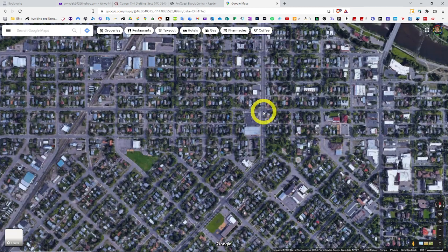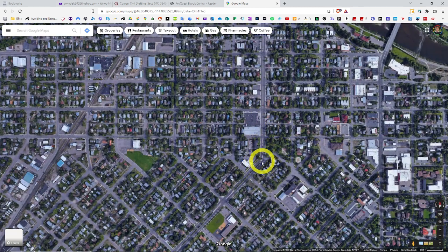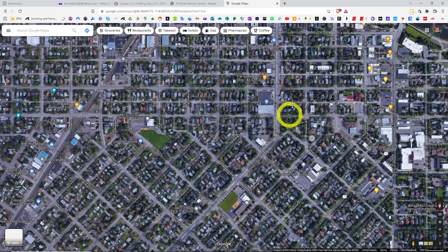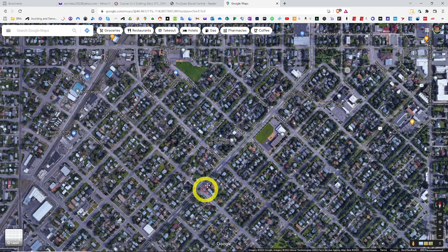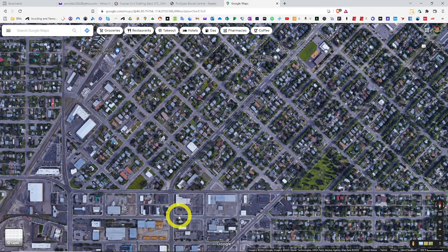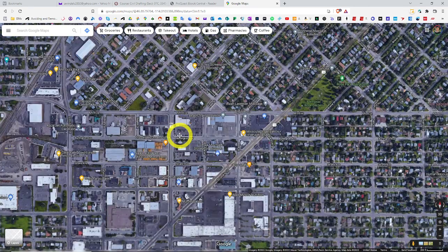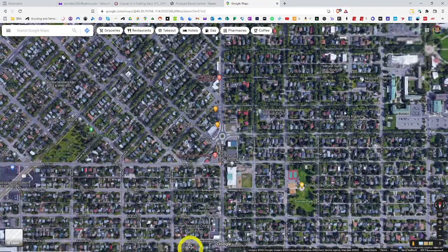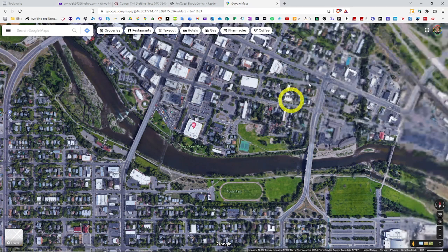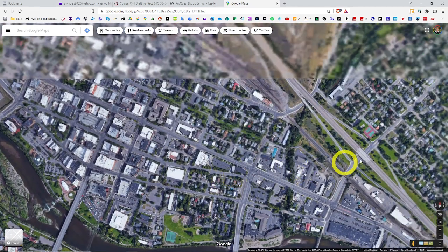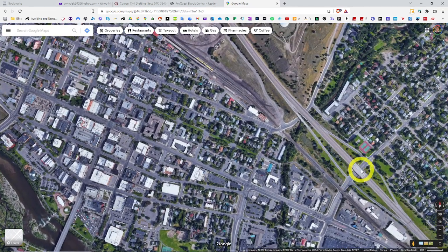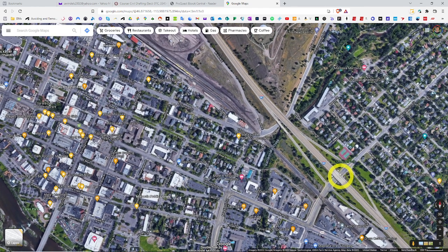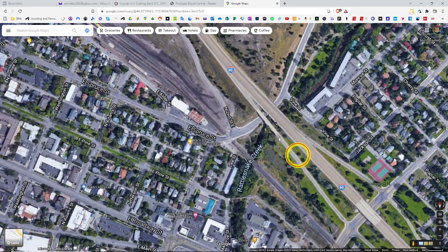You have this Orange Street here. There's a very tight curve in here. This isn't highway speed, but a lot of this stuff was laid in here very precisely from this kind of bird's eye view. There's a lot of curves and radiuses and various things going on. There's a lot of grid type roads too, of course. If you go all the way up to some of the more major arterial roads, some of the on and off ramps of this diamond intersection into the lower Rattlesnake, it's a little straight, but these are probably spirals coming into here. Gradual transitions as you get up to speed.